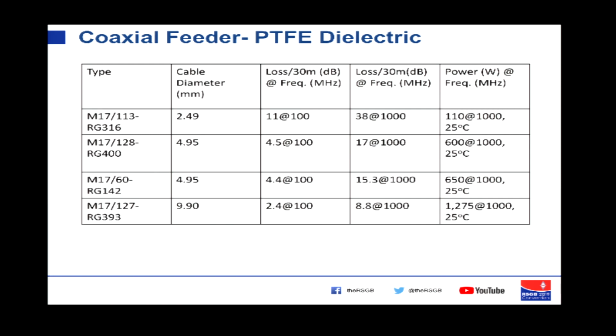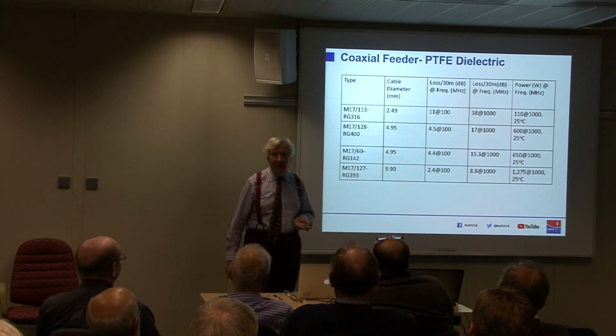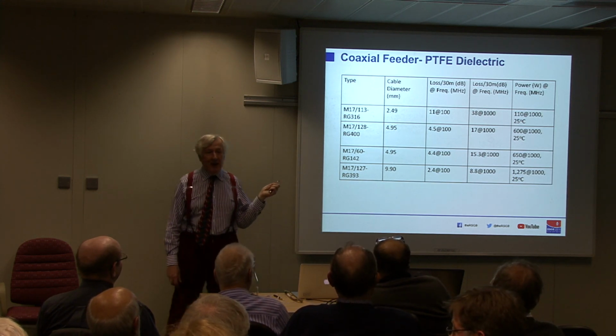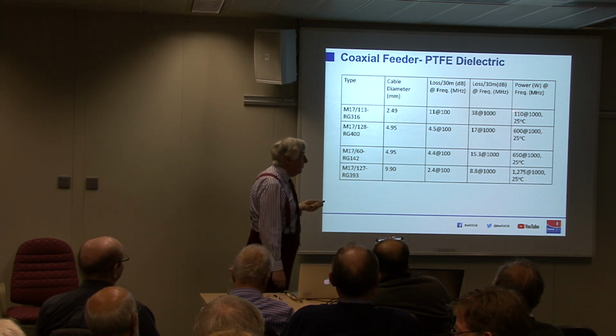Quite a useful cable. I mean, it's no use as a feeder, as you can see from its loss, but its power rating is remarkable. You can put 110 watts through it at a gigahertz through that little cable. I have actually tested to ensure that you can do that. I've done that experiment. You can. It gets quite warm. That is for warming the cable up to just under 200 centigrade, so don't touch it. But it will take that power.